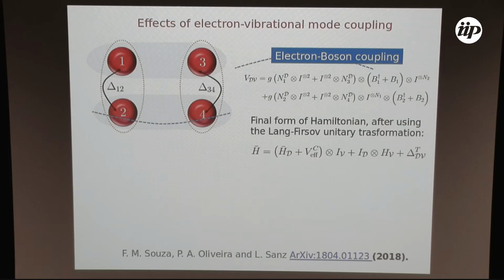Okay, but there is one nice feature here. Carbon nanotubes have many vibrational modes. For instance, if you have a single nanotube between two electrodes, they can vibrate like that, in the range of hundreds of megahertz. It is quite useful for telecommunication because it's in the range of telecommunication, and people are trying to build nanoradios using this kind of vibrational mode.